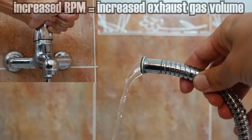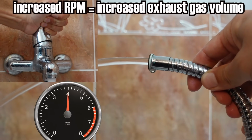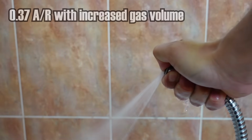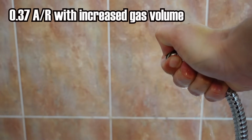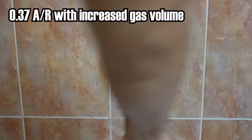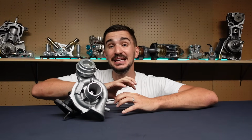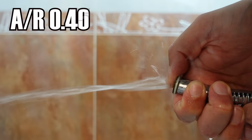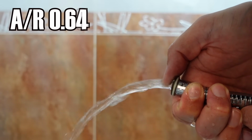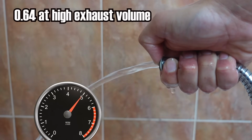However, as RPMs increase, we are increasing the maximum volume we are trying to push through a reduced opening, which means that small A over R housings at high RPM create an obstruction. They essentially choke the engine and reduce top end performance. Now, if we increase the A over R on the housings, we are increasing the cross section, we are creating more space, which means that we can push a greater maximum volume of gas.